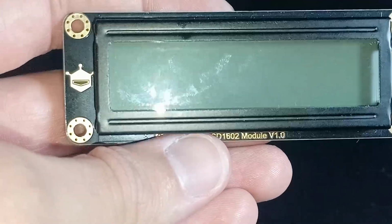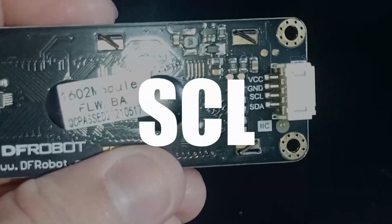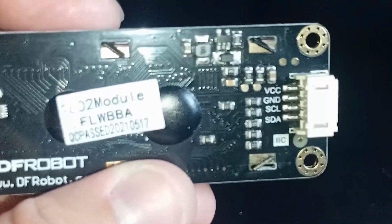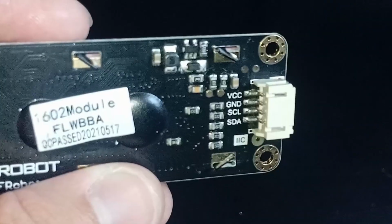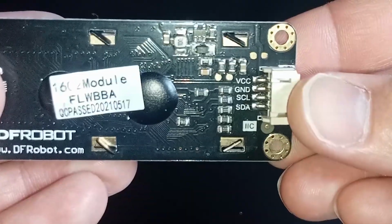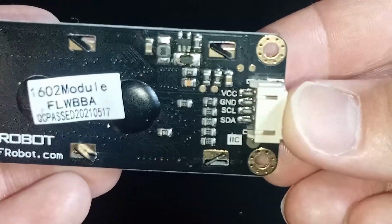Now let's flip the module around and look at the connector. You will notice 2 important labels, SDA and SCL. This tells us that this LCD module uses I2C communication. In an I2C setup, the SDA pin is responsible for data, and interestingly, it carries data in both directions. The SCL pin carries the clock signal, which is generated by the master device. In our case, the Arduino board is the master.